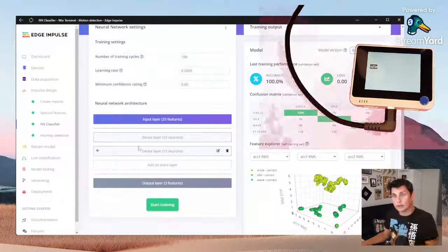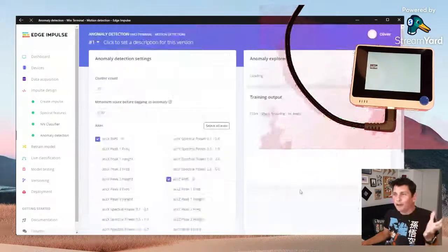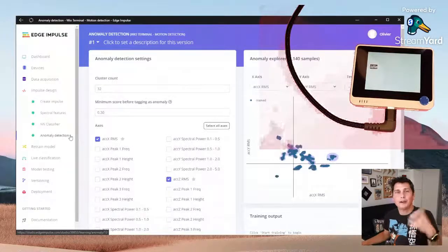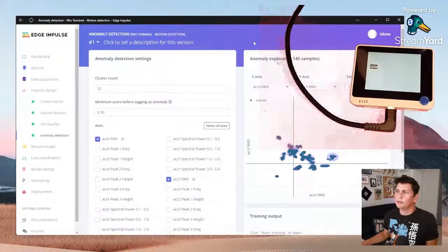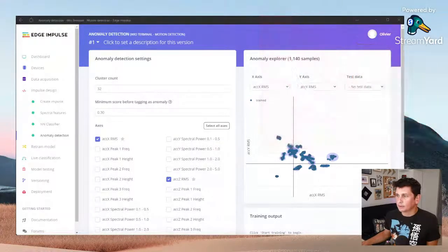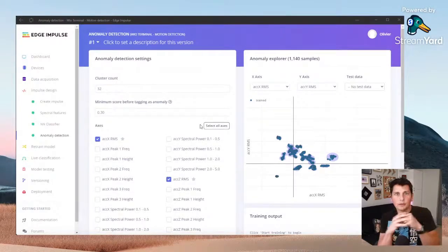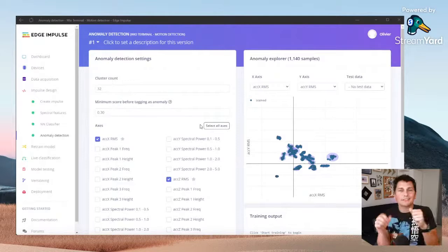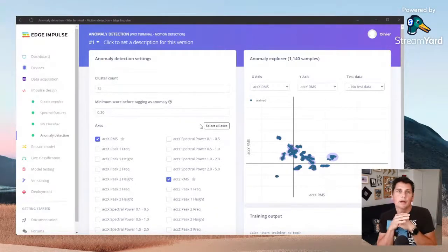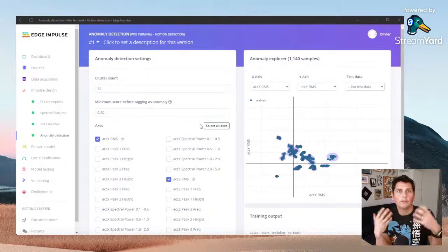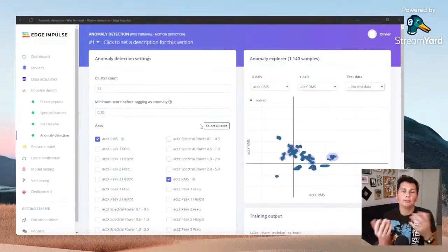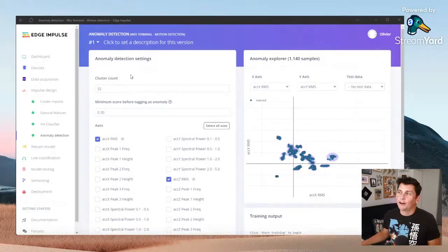And here you can see my device has been already working on that. Anomaly detection. Beyond having this classifier classify this data, what I can do as well is bring in, let me remove that for a second, I can add anomaly detection, because if I have only 3 clusters of results, but I have something that is not in there, imagine there's a motion I don't know about, then I can have Edge Impulse send me a score for an anomaly. Hey, I've never seen this. So chances are it's an anomaly, and that's also a result for me. And so I'm able to add this in the math for having an extra result that is the anomaly part.